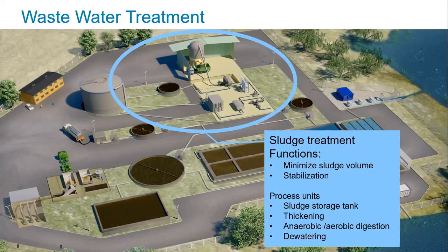So we use sludge treatment, digesters, dewatering, thickening to minimise the amount of sludge that we are handling. So that's the amount of sludge that's either going to be treated or taken and disposed of, or even reused, and potentially in some cases returned back into the process.